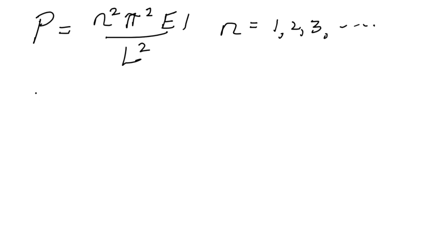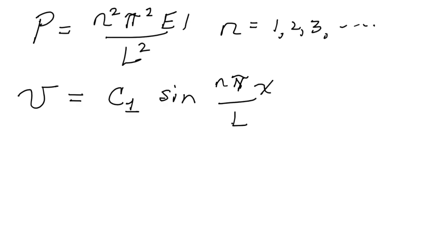And so that means that our final solution, V, our deflection, is going to be equal to C1 sine of n pi x over L.